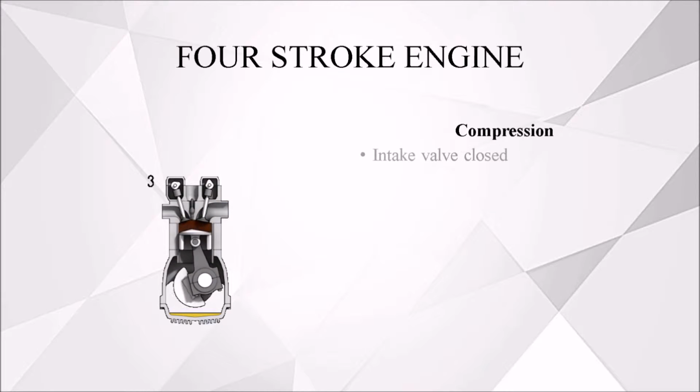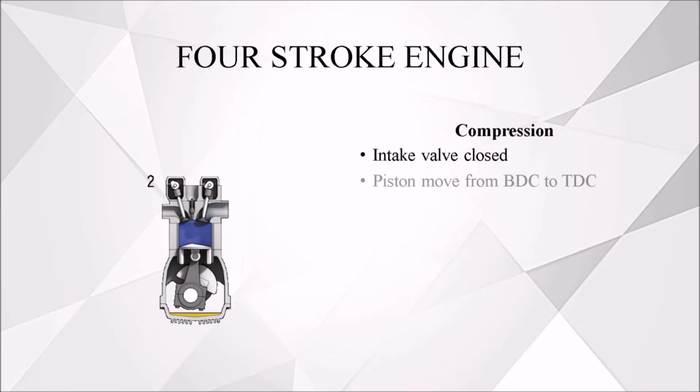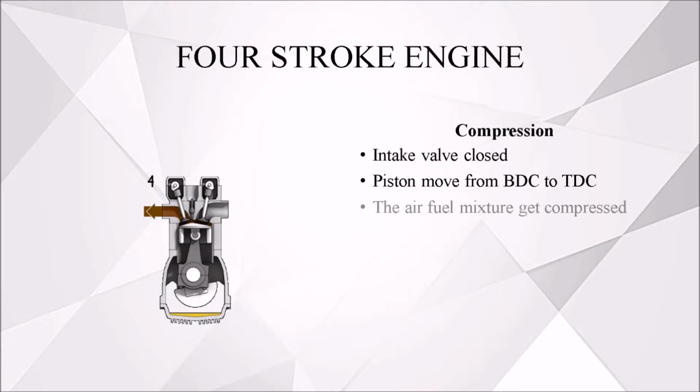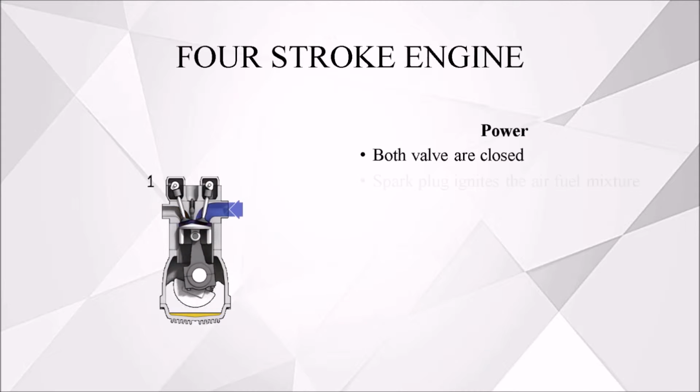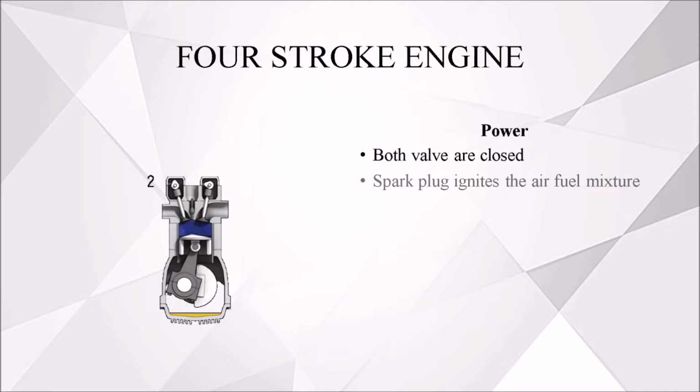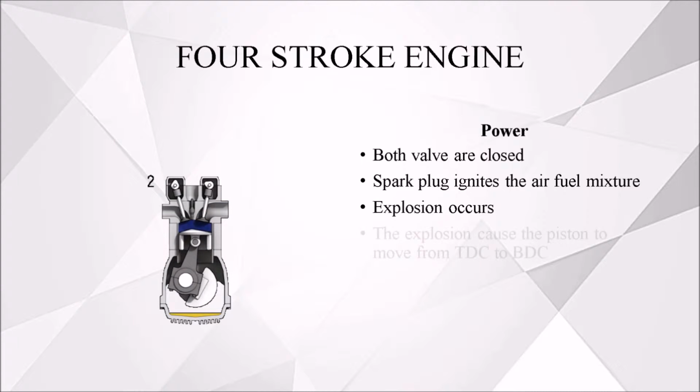Compression stroke: the intake valve is closed. The piston moves from BDC to TDC and the air-fuel mixture gets compressed. Power stroke: both valves are closed. The spark plug ignites the air-fuel mixture. An explosion occurs, which causes the piston to move from TDC to BDC.